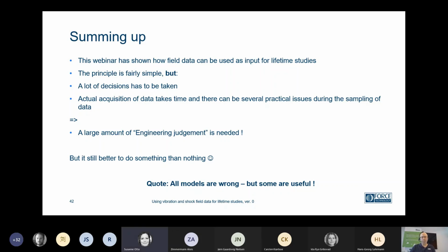Thank you. Another question from, I'm not sure if I get the Finnish name right, Juntunen Markku: how do you verify shock data? Basically, we record it, and then we do the SRS analysis. I have not shown any of the actual ones here today because I had to limit the amount of data I could have in one hour. But the SRS analysis is a very good way of comparing different shocks.